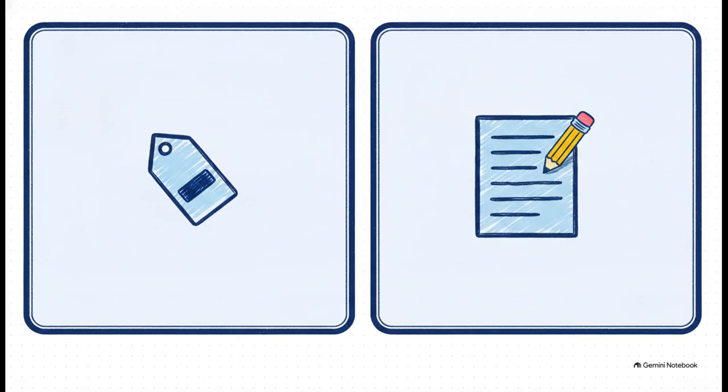Type text, or DT, to quickly drop a fixed height, single line of text. You literally just click for your insertion point, enter a height, type, and hit enter. Boom! Fast and absolutely perfect for simple standalone labels. But if you're putting together complex construction notes or a big paragraph of specs, you're going to need more control. That's exactly where multi-line text comes in. By typing mtext, or just T, you click and drag a bounding box to specify your width. That gives you a dedicated text editor, kind of like having a standard word processor right inside your drafting window.